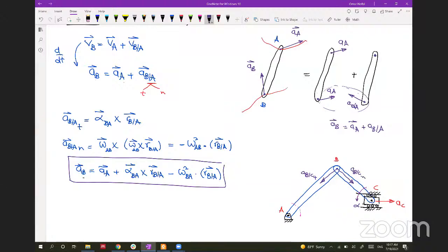So this is how we can get it at B. And if you finally want to know the total acceleration at B, you will get the root of the sum of the squares of the tangent and normal components, and you might find that the A_B is in this direction. So it's a little bit different from the velocity, because we have the normal components, and it changes everything in terms of the direction and the magnitude. So this is how different it is, and actually we use the alpha to get this A_B.